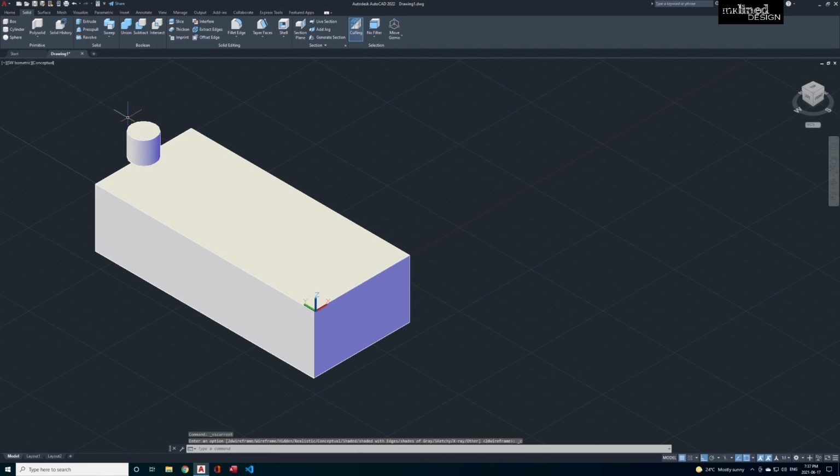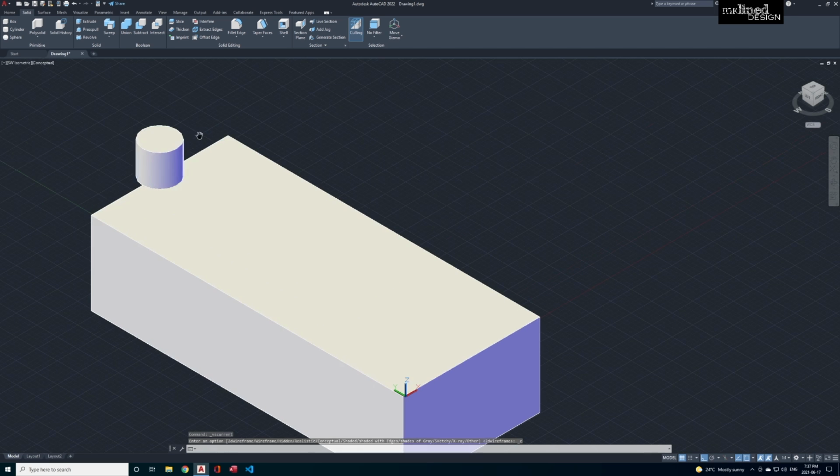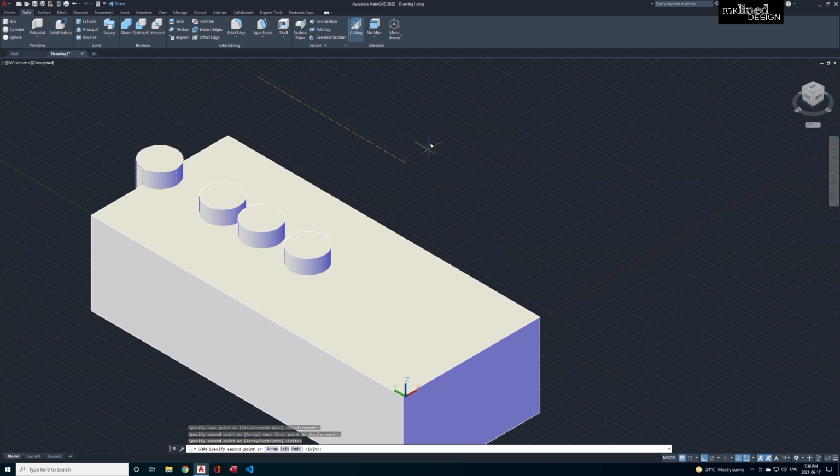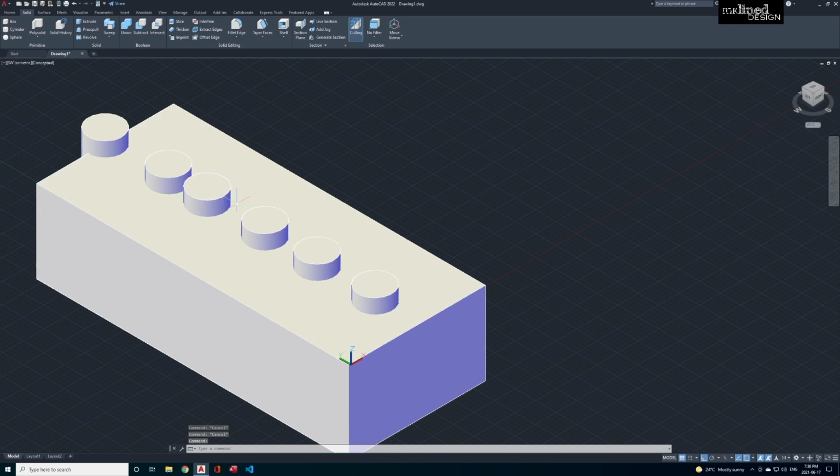So we have our cube, and then we want to punch a bunch of holes in it. So we'll move this down, and then I'm just going to copy it a bunch of times, randomly copy it down. Say we were making a control panel or something, and you could set those at what you want, but for demonstration purposes we're going to hit subtract.